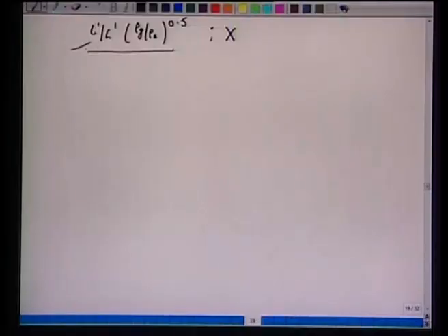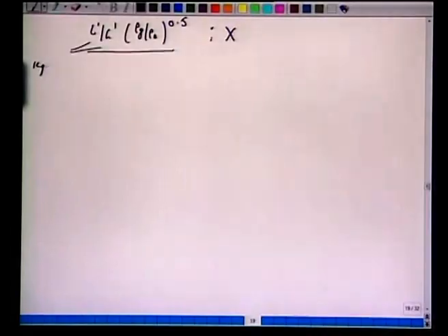So, L bar, G bar, now this is in kg per second per meter square, that is, per unit cross sectional area. That is what we are supposed to find out. So, that we get, and from there we get the diameter of this column. And the flue gas composition is given here. Let us calculate now G in kilomole per second. Excuse me. So, let us make it kilomole per second.